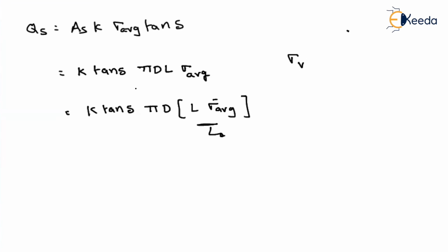Then let us draw the diagram again. Let us consider there is a pile. Imagine that it is vertical. And if I want to find out the variation of the vertical stress, there will be a water table here. This water table is at a distance of 2 meter, and up to 3.6 meter we have the critical depth. So if your water table is here, then what will be the remaining depth? 3.6 minus 2, so from here to here, the remaining is 1.6 meter, right?